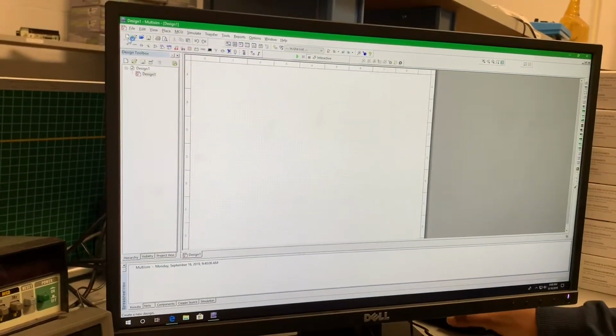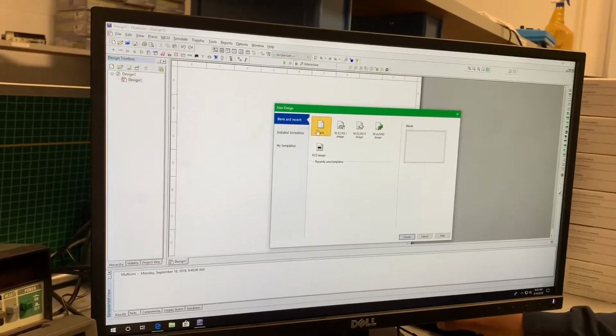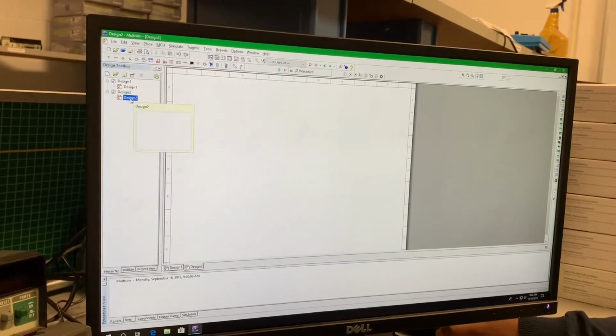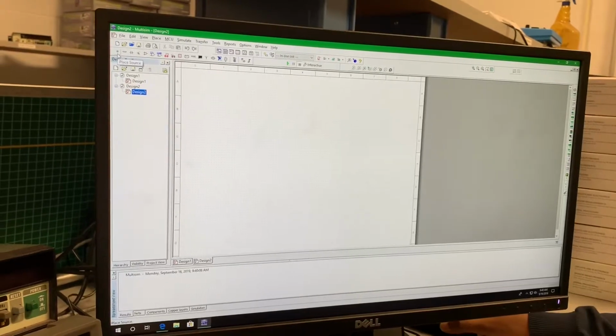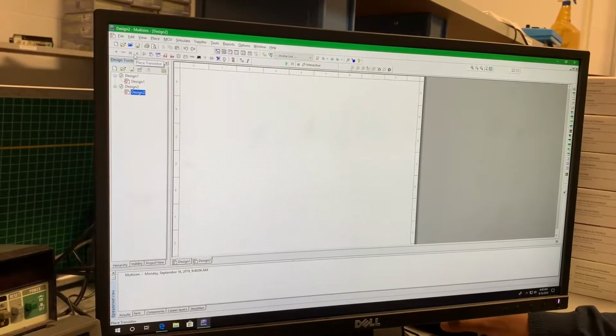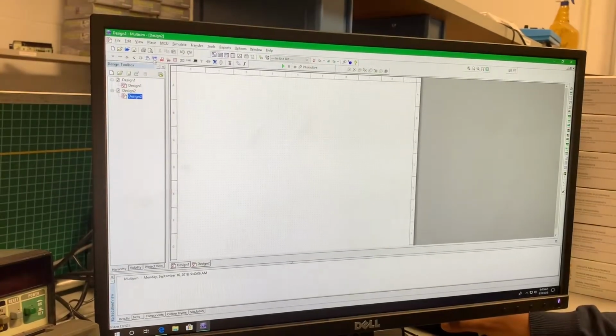And then anytime you want to start a new Multisim project, you'll go to New up in the left corner. You can start a blank project and hit Create. We can see that it made it a design 2 for us because there was already one open. But then right below that, you'll see your components, and you can place a source, place a basic component, diode, transistor, analog.